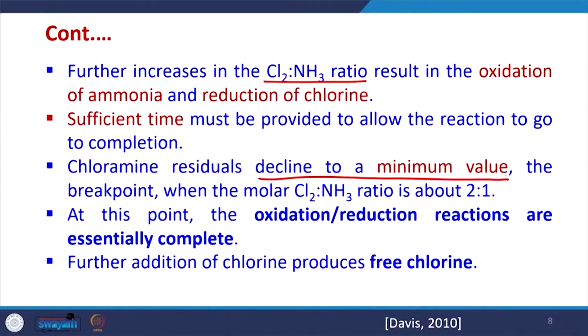So, the chloramine residuals thereafter decline to a minimum value, and this break point will be there around the molar Cl2 to NH3 ratio of 2:1.